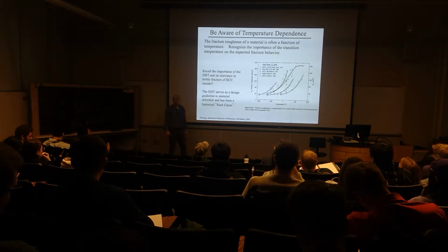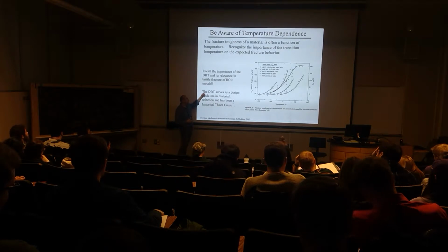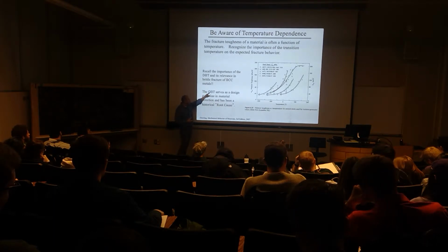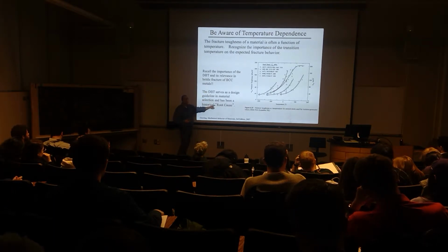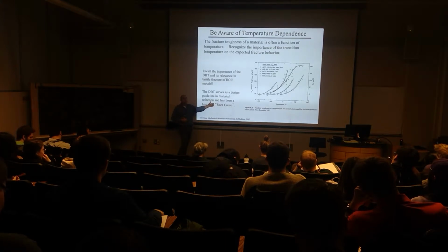So you want to look to see which temperature is important in that particular fracture for the material. So you can find that just inappropriate choice of the material and its DBT point in comparison to the environmental temperature can be the real root cause. Fracture is just what happened, but the cause is that it was the temperature and the material was chosen inappropriately for that particular environment.